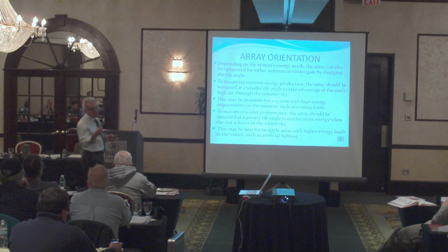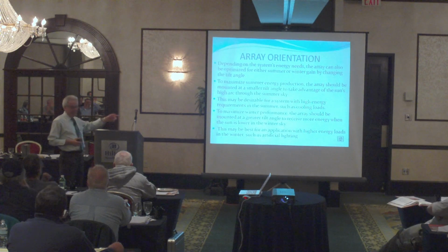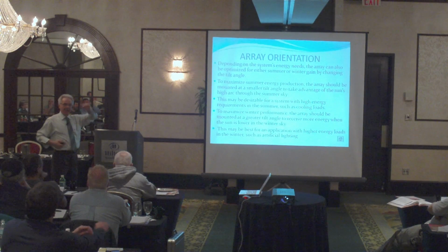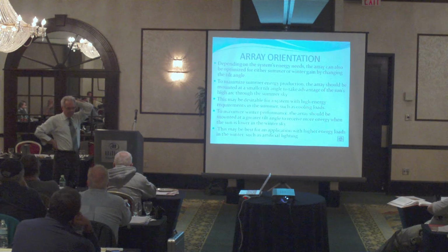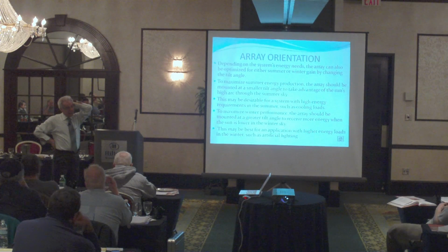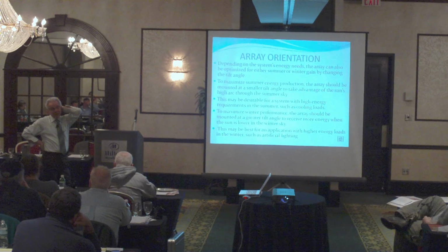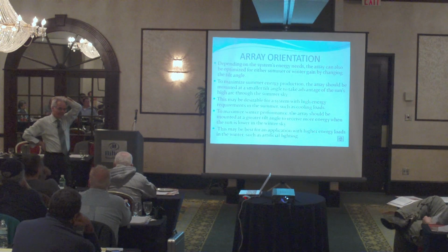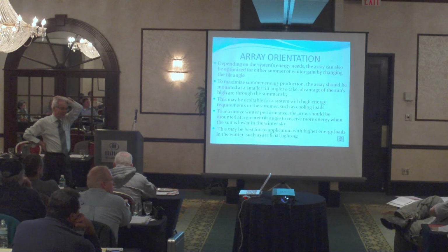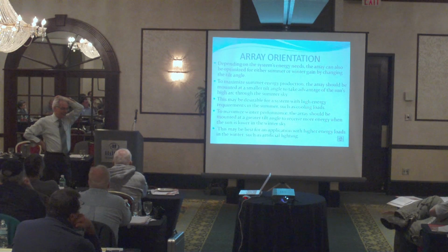Well, two things. One is the need. The other thing is, I think it could go as much as 30%. But don't forget, it depends on the size of the system you have. If you have a fixed 3 kW system, you're going to gain 10%, 20%, 30% by adjusting the angle. That's what I'm talking about. Folks said 40%. That's optimal, yeah.